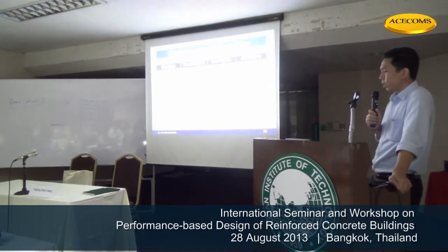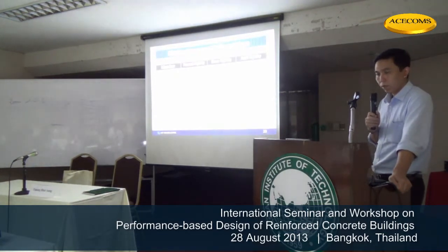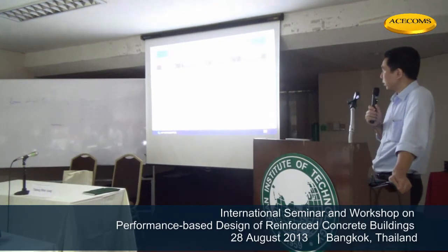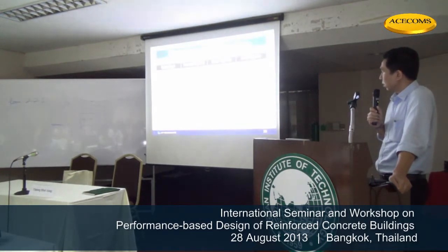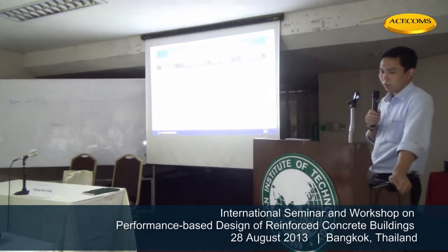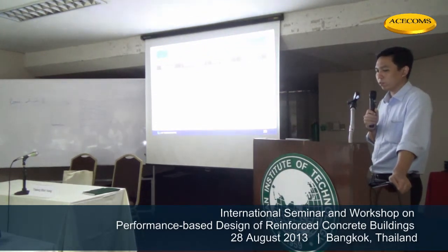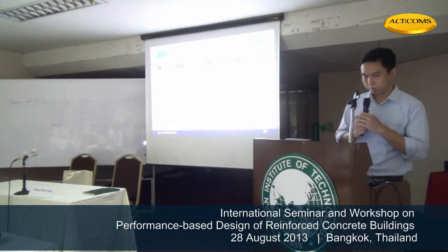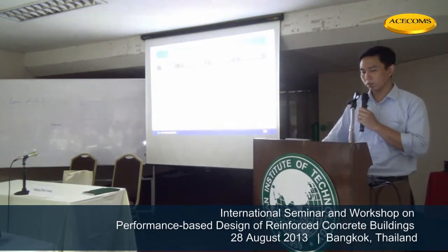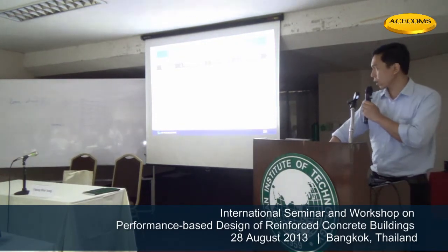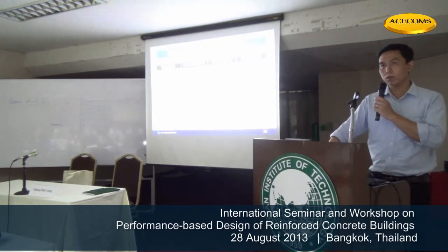After doing the detailed design, we check the service level evaluation of the building. Normally in the code-based design procedure, if we design according to the code using a 475 year return period earthquake, the code assumes that the building will remain elastic and serviceable at a 43-year return period earthquake, which we call service level, and also it will not collapse for the very strong earthquake.